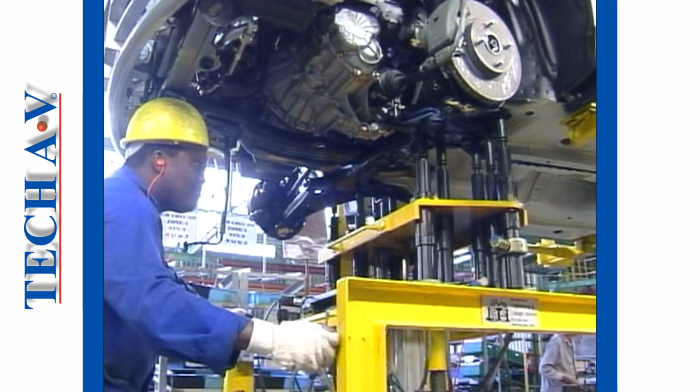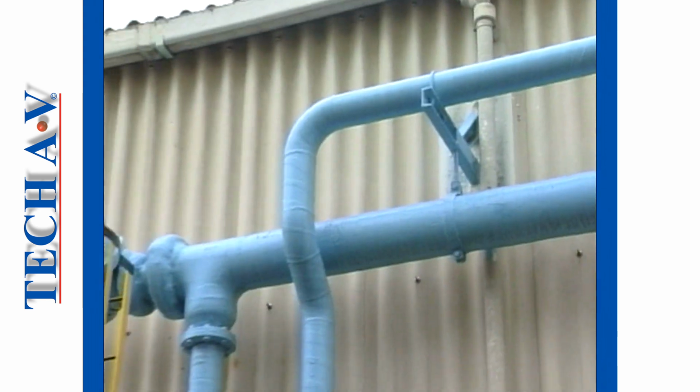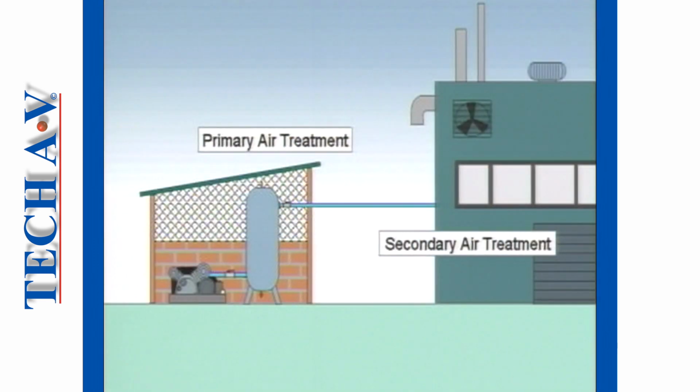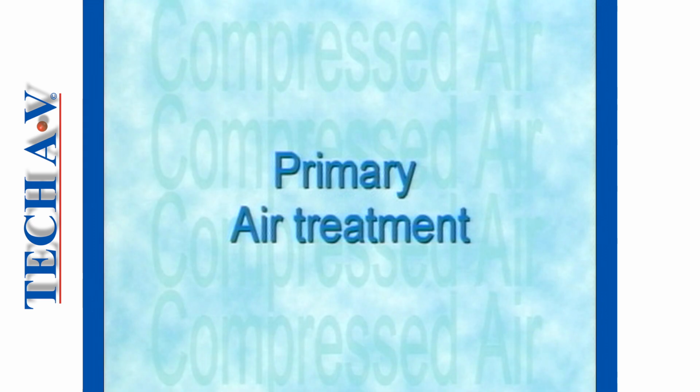In most industrial compressed air systems, you will find two categories of air treatment devices, namely primary air treatment devices and secondary air treatment devices. Let us look at primary air treatment. The term primary air treatment refers to the removal of contaminants before the compressed air enters the air main.